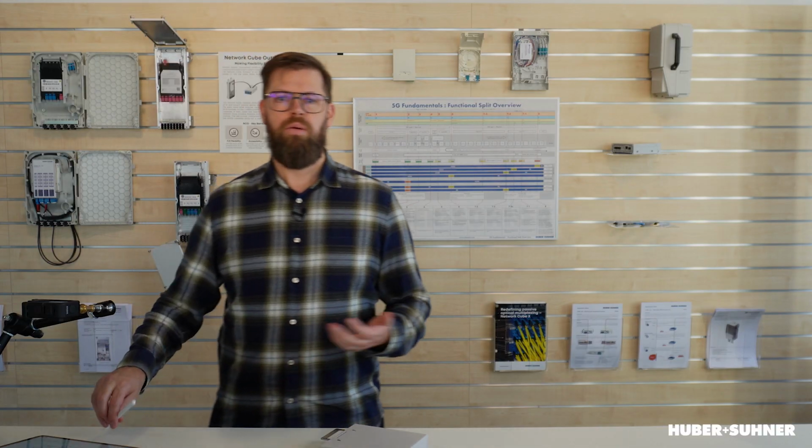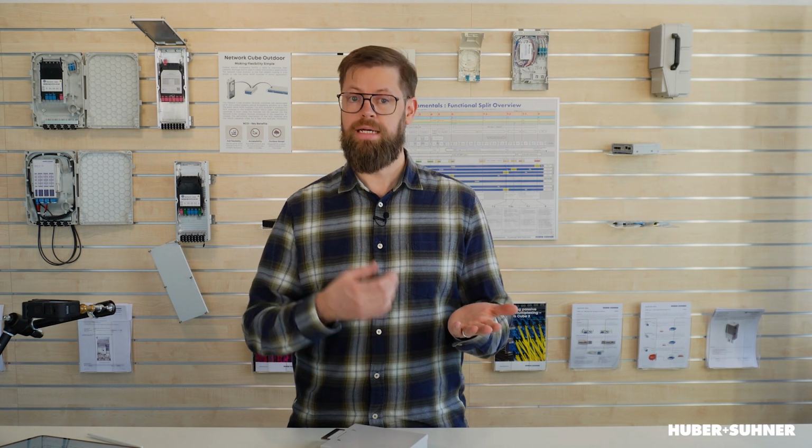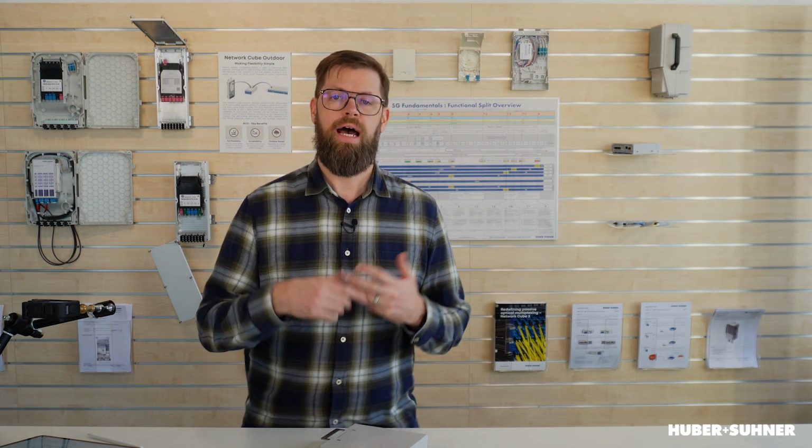the worst case scenario. When we're talking about a WDM setup, we're normally talking about a link. In other words, we've got a multiplexer and a demultiplexer. And this is where the link loss comes into play, because the link loss describes the accumulated loss through the multiplexer and the demultiplexer. And that makes the link loss value ideal if you're calculating the optical budget of a WDM link.